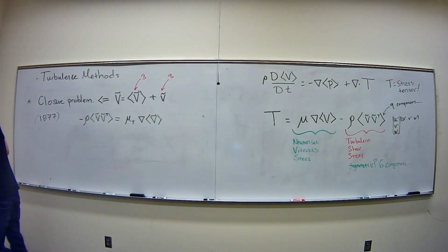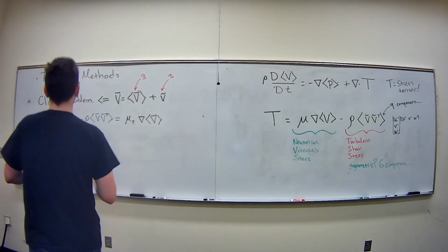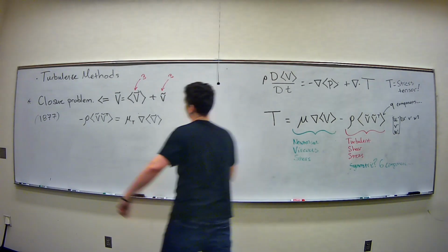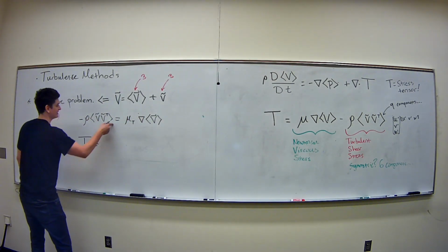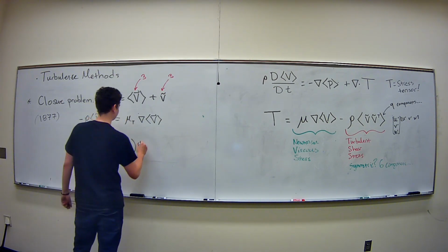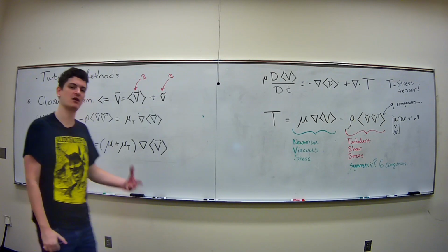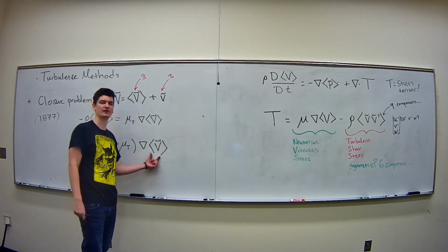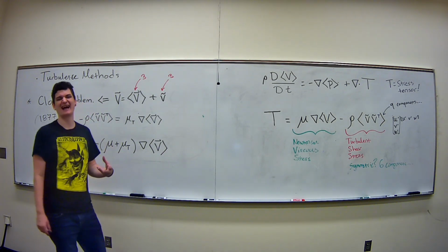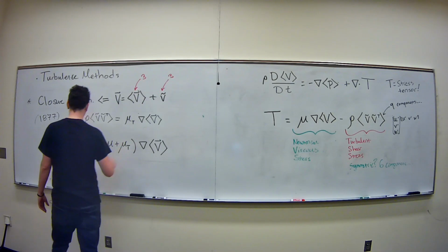It works okay, but I like this assumption, this very old one, because it still permeates so much of turbulent theory. What it says is, at least in this case it ends up working, that this term ends up looking like this. If I have this true, well, what does it look like? Then you get this theory where you remove your fluctuations, and I can close the problem and just see how that mean flow evolves. And the mean flow evolves differently because the effect of turbulence can be characterized as an added viscosity. It's pretty powerful, and it's one of the simplest models you could have, right?